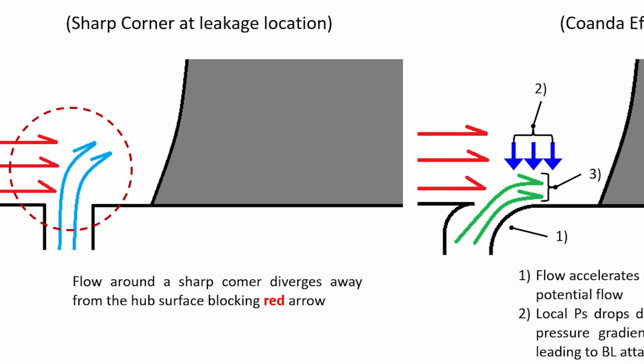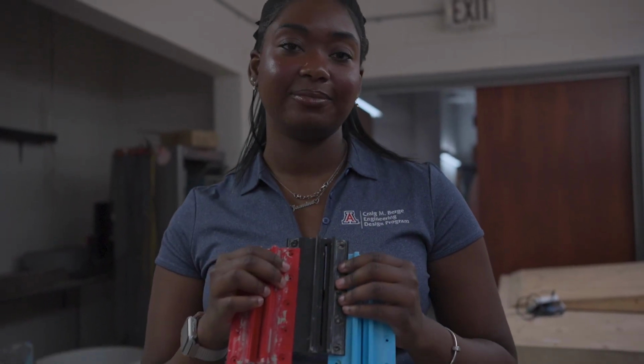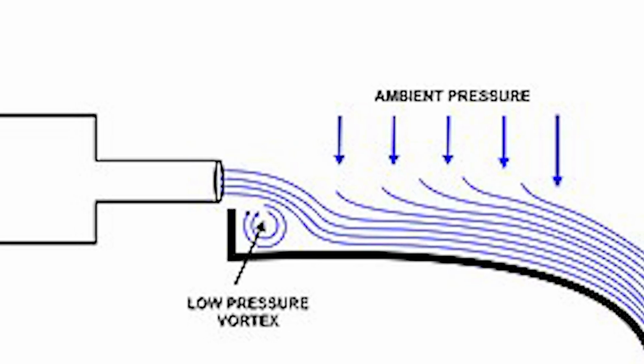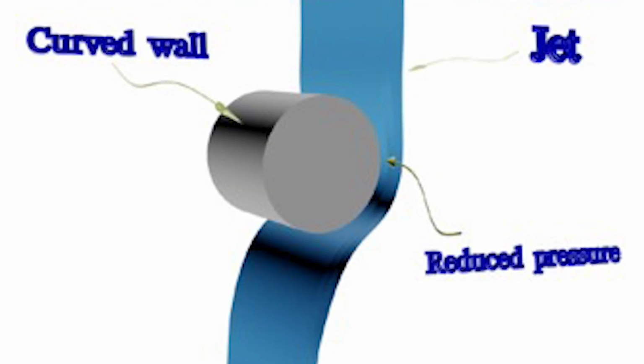increasing fuel burn. The goal of this project is to investigate alternative injection methods that employ the COANDA effect to analyze their impact on the downstream pressure gradient. Put simply, the COANDA effect is a natural tendency for a jet stream to attach to a nearby curved surface. Surrounding air gets pulled along by the jet's curved path, also known as fluid entrainment.